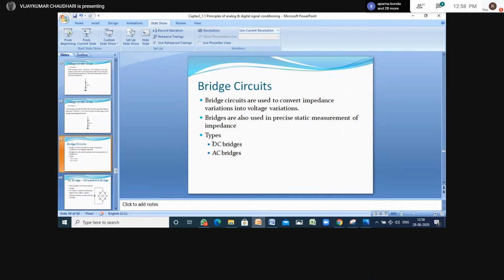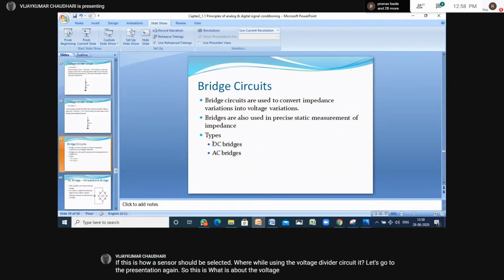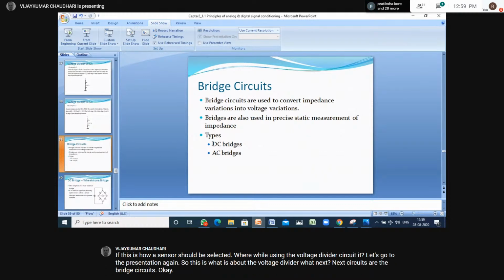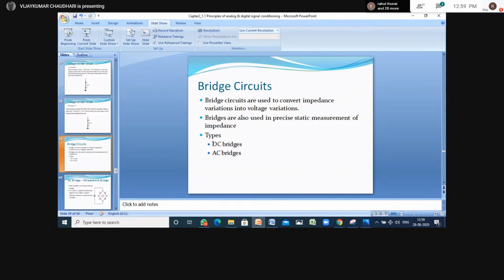It's a flat film type device, fixed to the beam. When the force is applied, the dimensions of that strain gauge change. It changes its resistance, and the strain gauge is an arm of the bridge. So the bridge becomes unbalanced and it gives some output voltage. This output voltage is then amplified or attenuated and all conditioning is done, and the stress and strain in the beam can be calculated.